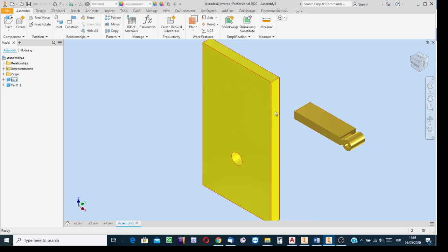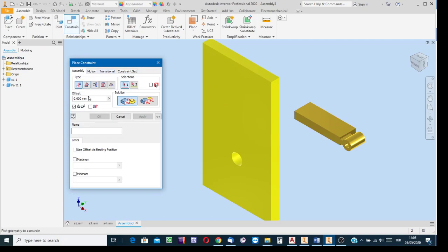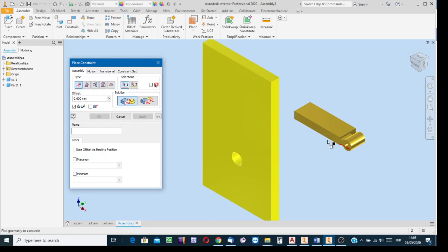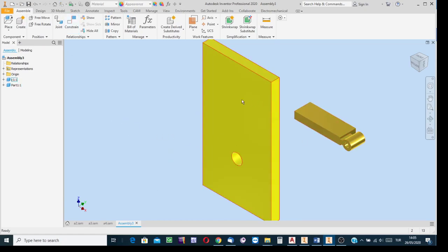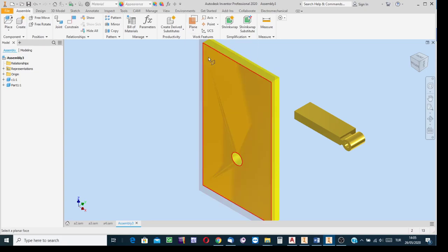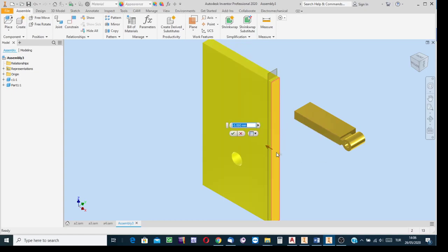Okay, yes, if the surfaces to position are the existing surfaces of the components, it's okay. Then, for instance, select this constraining tool and then say that this surface and that surface are to be positioned, or change the order, this surface and that surface. Yes, it is okay. But here say that not those surfaces are to be used for mating one component with respect to the other, but any other. Say the other case, for instance, work plane. Have a work plane. I'm going to make the demo selecting this as the reference and then say that a work plane. Have such a work plane over here.